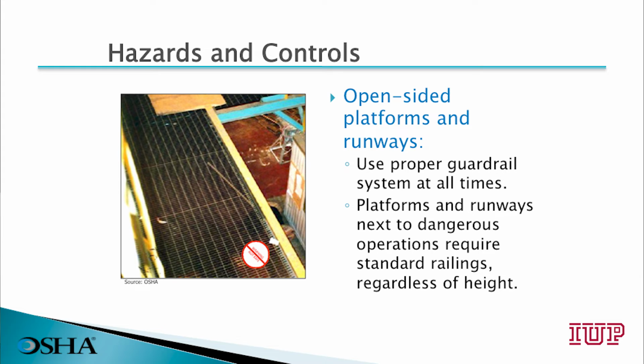Additional hazards include any open-sided platforms or runways. We need to use proper guardrail systems at all times. And platforms and runways next to dangerous operations require standard railings regardless of height.